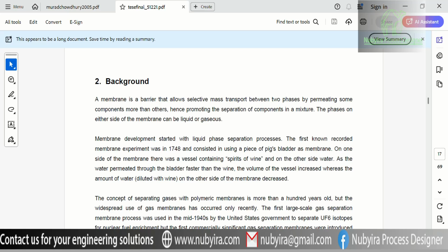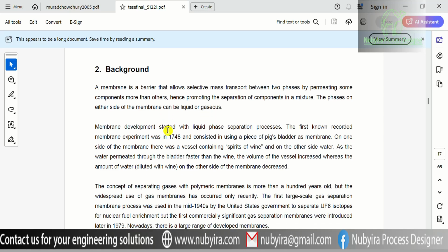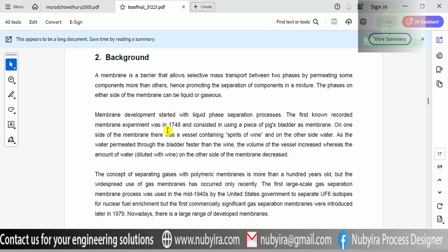For example, when you have a mixture of gases that you want to separate, you can send it through a semi-permeable membrane that allows some components to pass through, while the rate of diffusion of other components is very low. With that, you can separate them by using a high pressure pump that will create a pressure differential across the membrane.